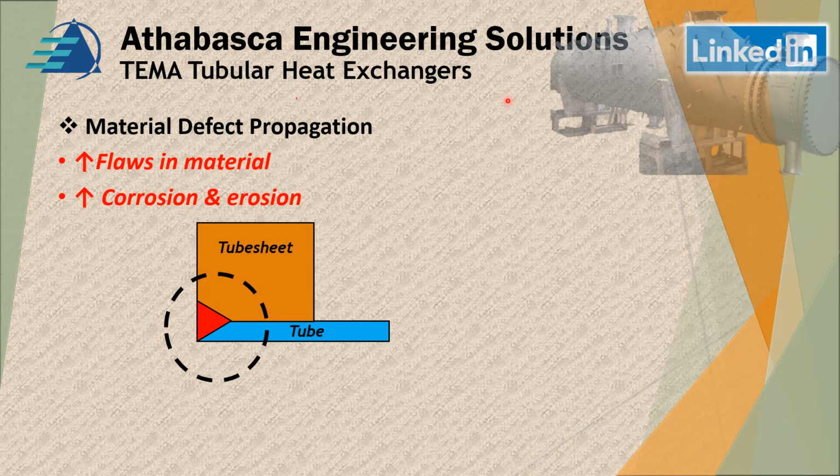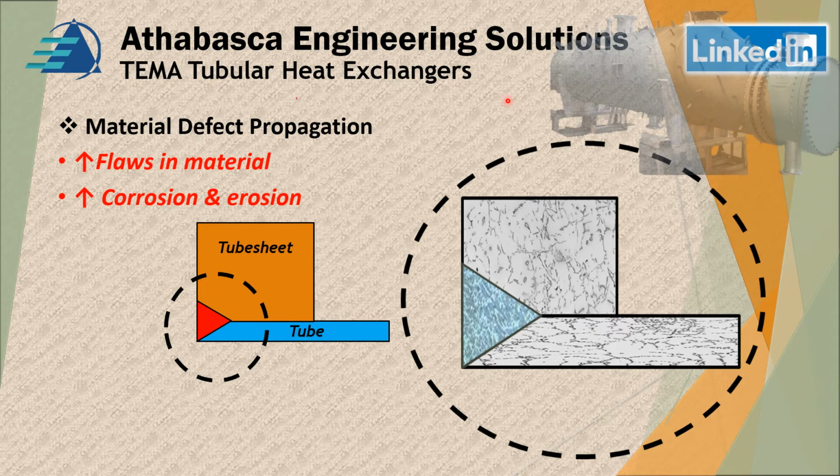Now, this is where the tube is, where the weld is on the tube sheet, which is susceptible to defect propagation if the welds are not done properly. What I've done is show a microstructure and superimposed what the grains would look like. On the weld side, that triangular part over here, we get what's called a Widmanstätten grain structure, an effect of fast cooling on the weld.